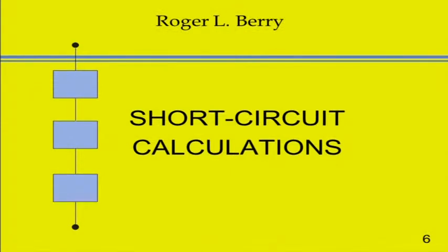And we're going to come back and talk about short circuit current calculations in a few minutes and look at the math and how we do the math to find out what kind of fault current is available. Today, more requirements are in place that people have to, when they build a facility, label the equipment more today than ever before with the kind of fault current that's available, short circuit current that's available. And then equipment is sized to withstand what can go through it.